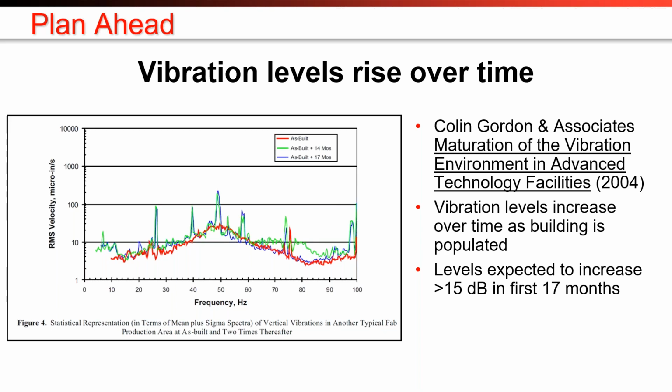So this is important because decisions can be made at the time the building is open, right? When the building is opened and things are just getting started, if floor vibration measurements are taken and it's determined that a particular spot in the building meets the vibration criteria of an instrument that's going there, that may be true when it's first installed, but you could easily have a situation where a year and a half later, that tool is not meeting its performance specs because the vibration levels exceed the vibration specs of the instrument by 15 dB or potentially even more.